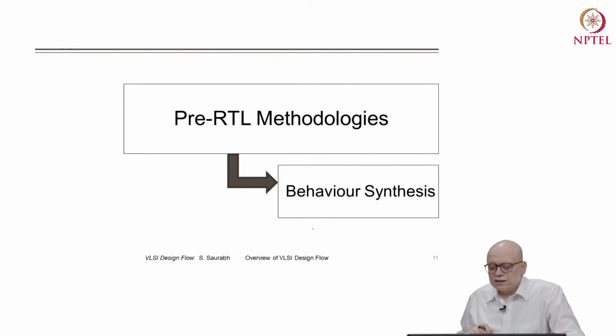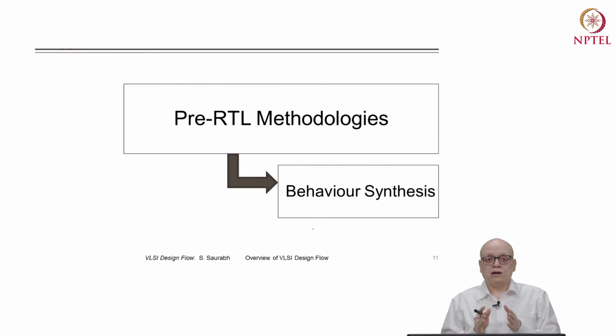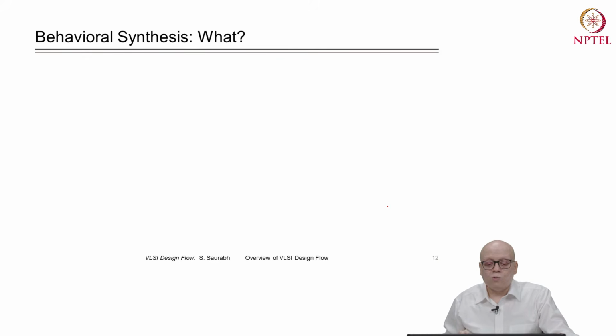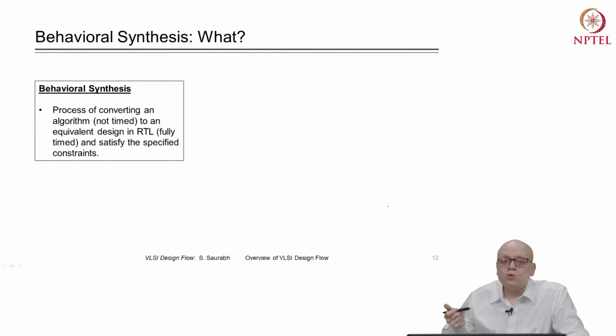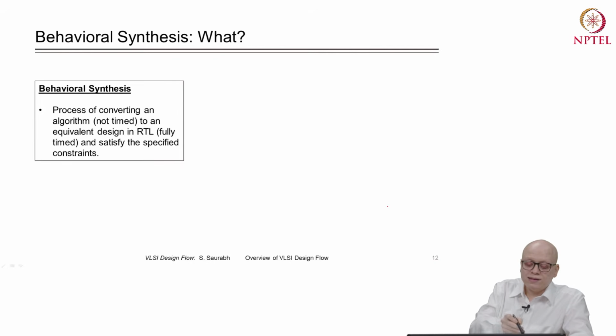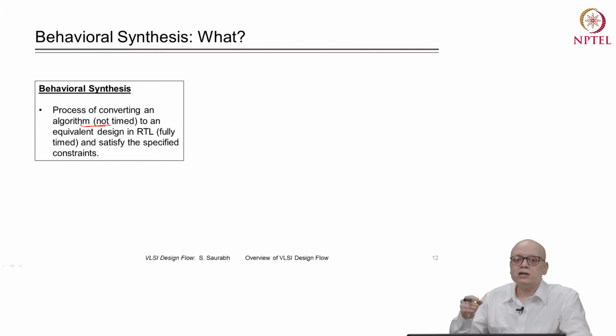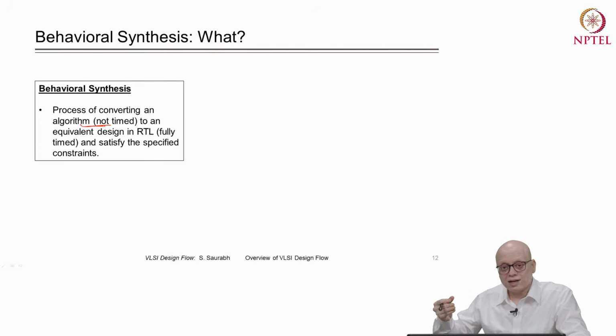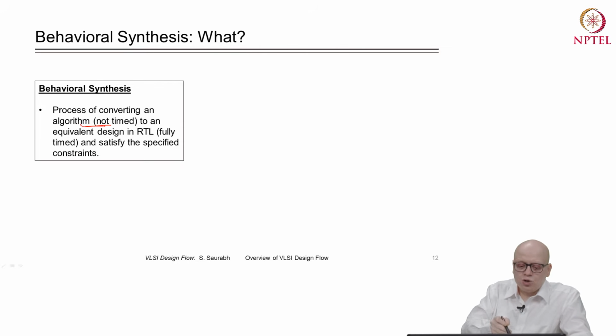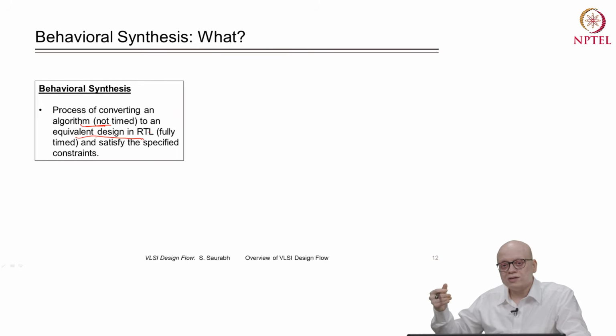Now, the other way in which we can convert functionality in a high level language to an RTL is behavior synthesis. Let's first look into what behavior synthesis is. Behavior synthesis is the process of converting an algorithm which is not timed, meaning it doesn't carry timing information, meaning which operation needs to be performed in which clock cycle, that information is not there, to an equivalent RTL design which is fully timed, meaning that it says how the computation is done in which clock cycle and so on, right?